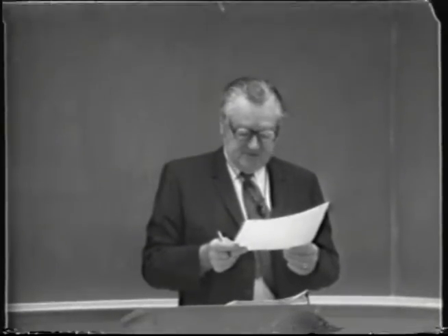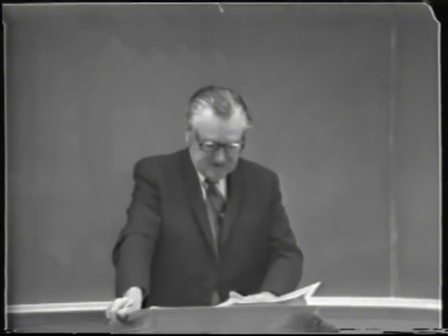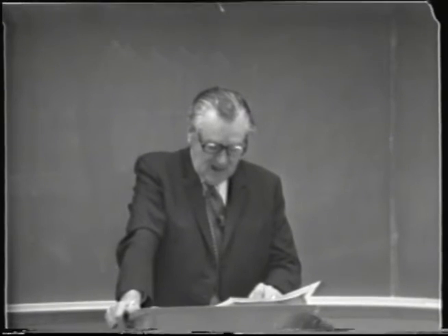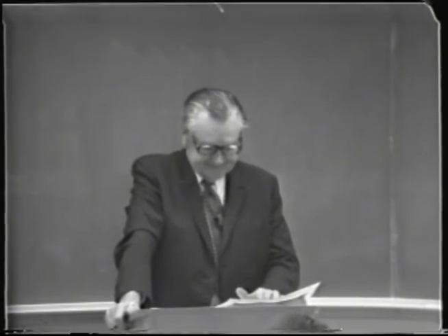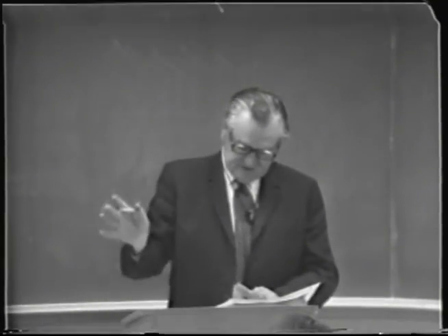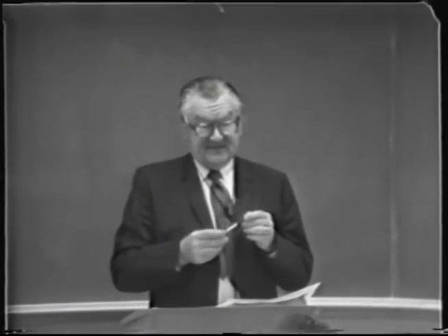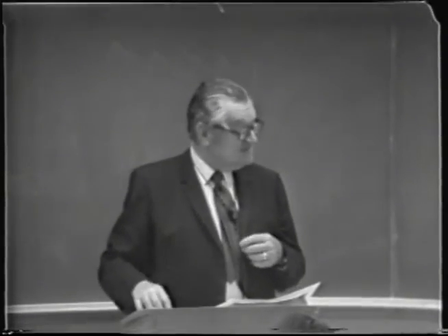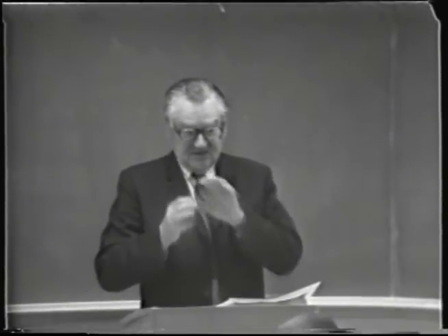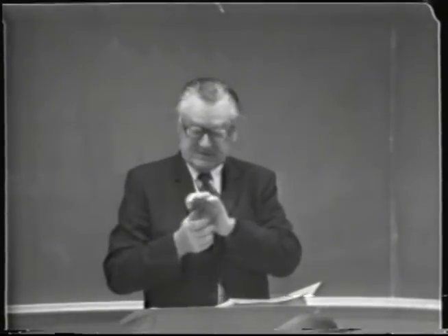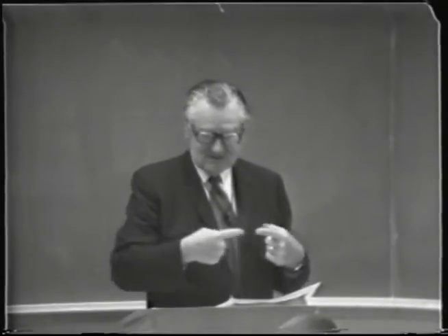Now maybe it's time to turn to the bottom of the right-hand page there where it refers to that drawing, figure 1444, where it says high-pressure steam is caused to expand in the nozzle, A, from which it issues at a high velocity into the mixing space, B. I think you'll recall from physics and maybe physical chemistry that if you have a fluid traveling at high velocity, whether it's air or a liquid, usually it induces a low pressure at the lateral.